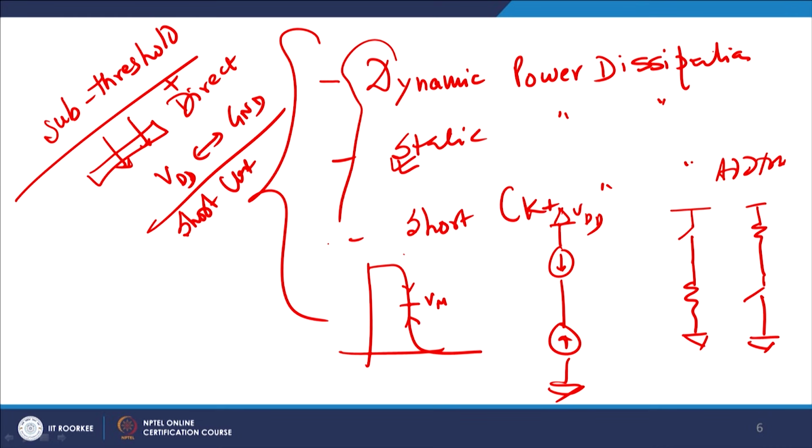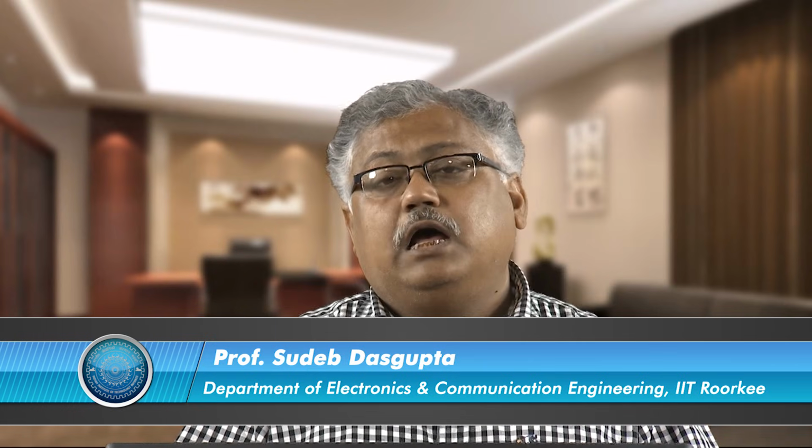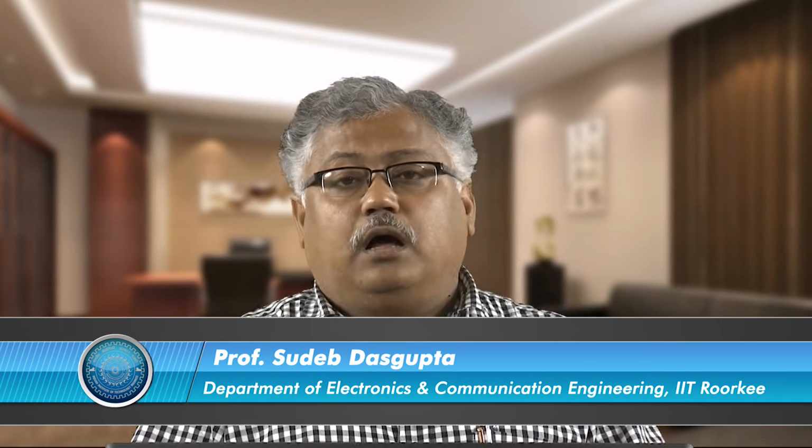With this idea I would like to stop here today. What we have discussed today is basically the inverter characteristics. We have understood the static characteristics of an inverter, how to draw the VTC, voltage transfer characteristics of an inverter, and how to extract noise margins from an inverter. We have also understood the basic building block of an inverter, what is the propagation delay of an inverter, what is TP-HL and TP-LH, how they are related to VDD and R equivalent and CL, how I can minimize the delay across an inverter chain, and what the sizing ratio should be so that these can be modified to a proper extent.